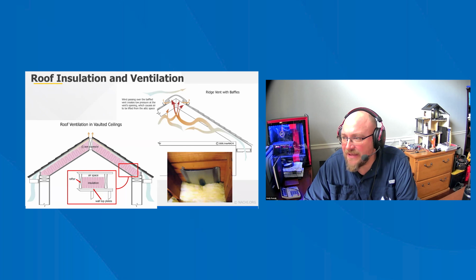And in the case of ice dams, elevated attic and roof temperatures during the winter can cause snow on the roof to melt. Insulation and roof ventilation help to keep the roof's exterior surface cold and minimize the development of melted water and consequently ice dams. Ventilating roofs in hot and humid conditions may add rather than remove moisture from attics and enclosed roof spaces. However, not ventilating a roof may void the manufacturer's warranty and slightly decrease the life expectancy of asphalt shingles due to the increased temperature of the roof surface.